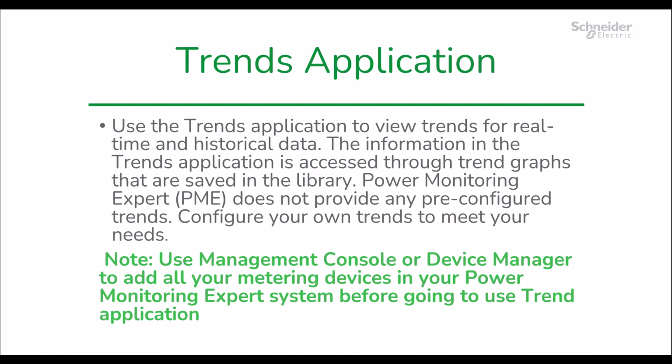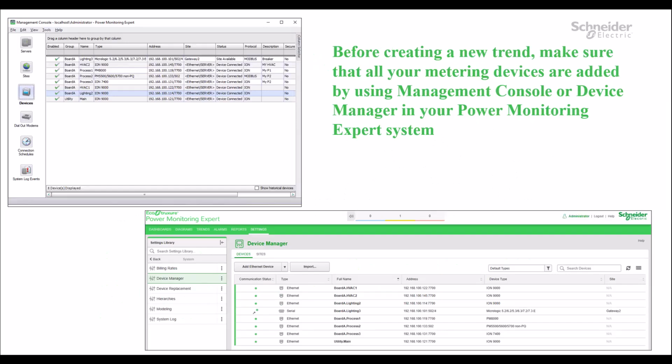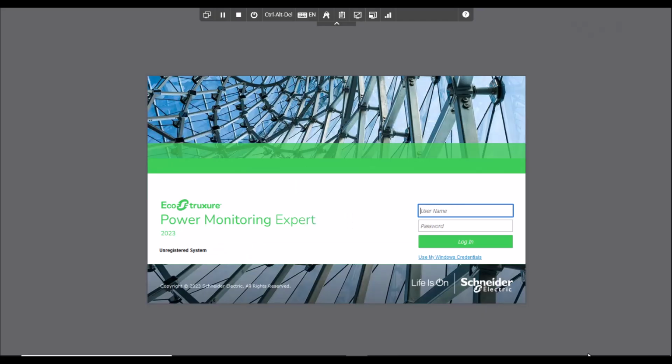In this video, we will look at the Trends application in the PME web client and how we can use it to monitor our system. Before creating a new trend, make sure that all your metering devices are added by using Management Console or Device Manager in your Power Monitoring Expert system. We will see how to create and configure trends.